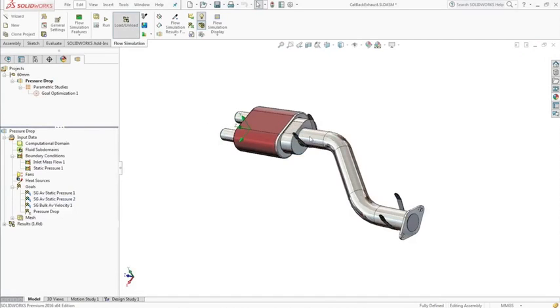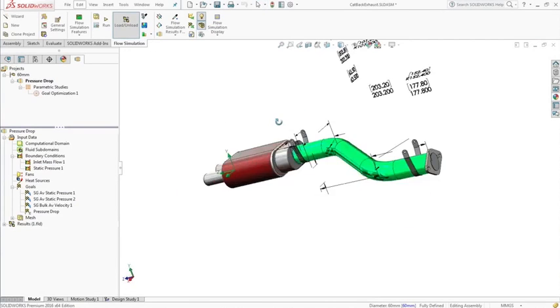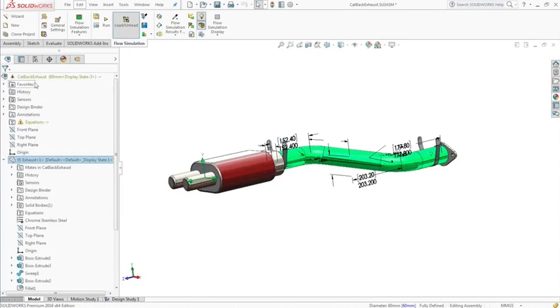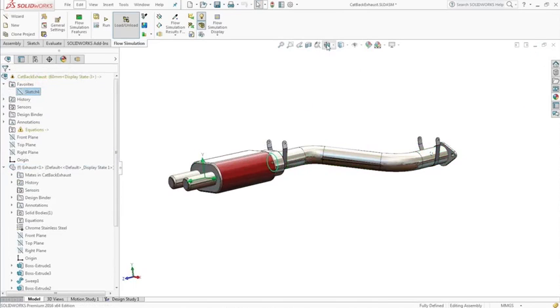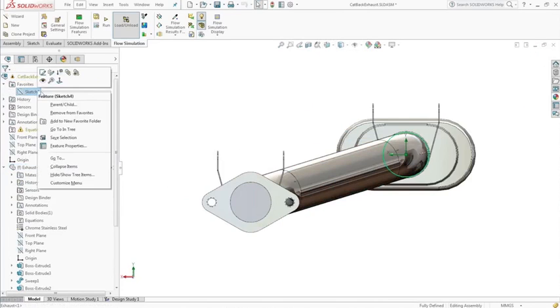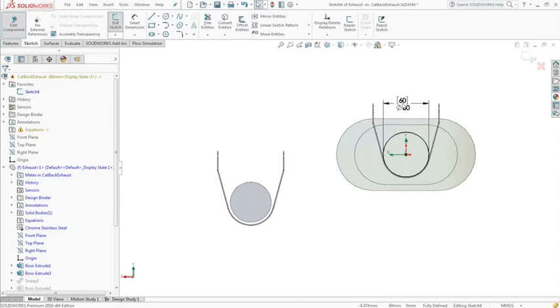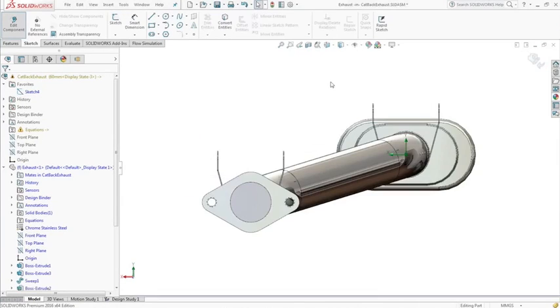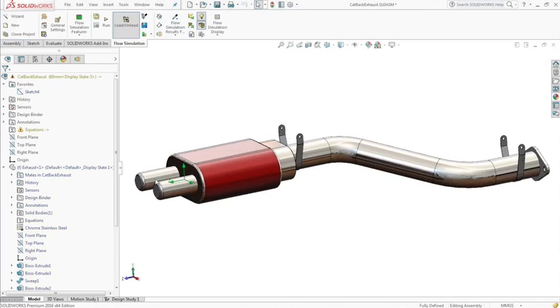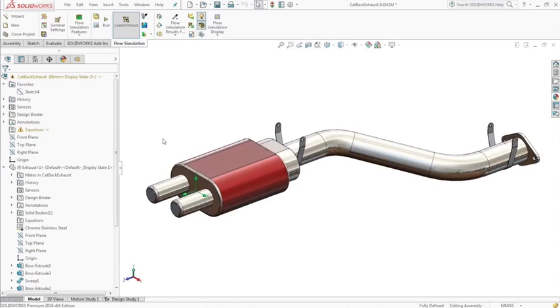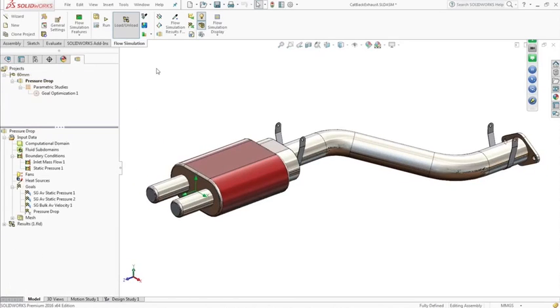And in this situation, I've started with 60 millimeters here. You can see again, I've got the sketch profile saved to my feature tree, and I can go take a look at what that is. So 60 millimeters for the diameter of the tubing, and I've also got some creative modeling techniques in here where when I modify that, it's also going to adjust the diameter of the exhaust tips, just to make sure I got sort of the same cross-sectional area.